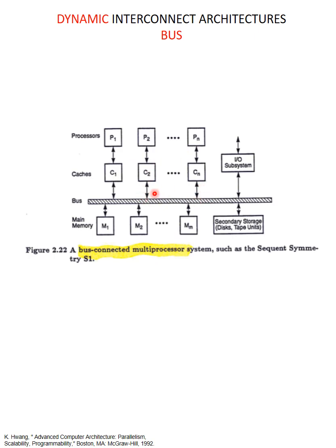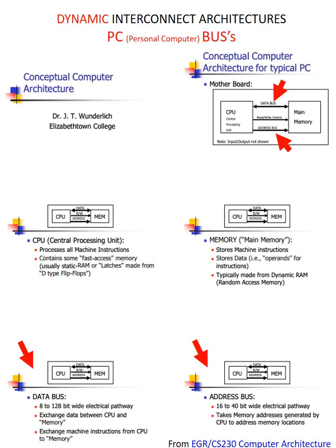You need tri-state buffers or some kind of isolation to electrically not have everything connected all at once. But the beauty of it is everything can connect to anything else. It's not quite as scalable as some other dynamic architectures, but it works pretty good in most cases until you get too many things trying to talk to each other.